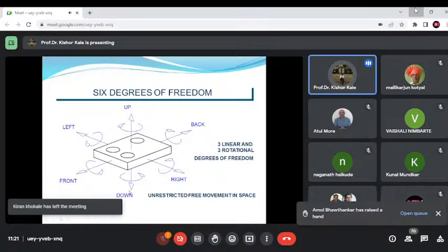When we specify two points on plane B to define the secondary datum, we lock two degrees of freedom, and only one point is required in plane C, because the third datum plane is established by one point only. That means by just defining one point on the third surface, plane C is defined.